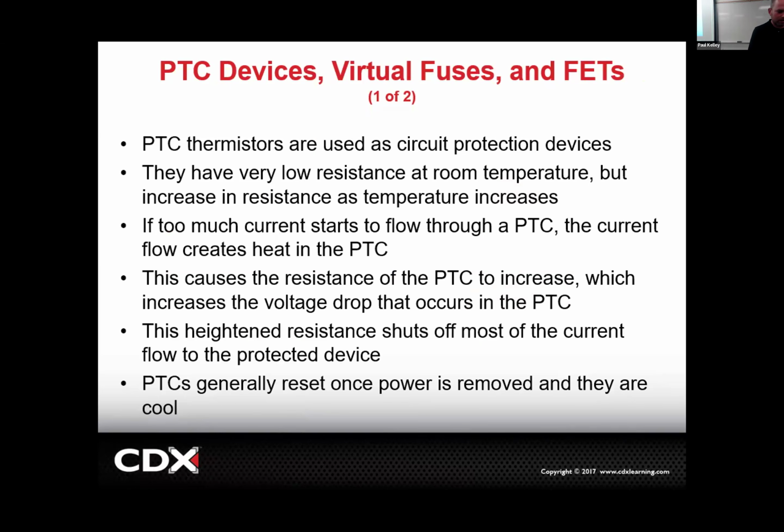And those, depending on temperature, will either have high resistance. If it gets too hot, it'll have high resistance. That'll be like an open. And then when it cools down, all of a sudden, boom, it'll close and it'll have continuity and the part will work again. I bring these up because they can be very small and we can simply have them inside of a motor, right? So if you think you had a problem with a PTC circuit breaker, you'd be looking all over for it.